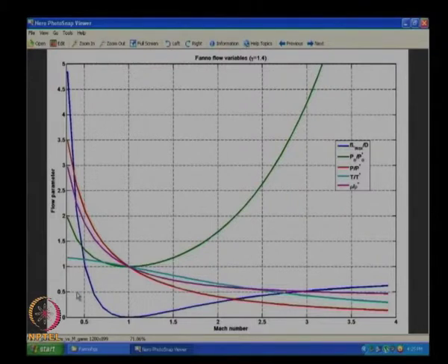That also says that if, let us say, the L max was 1 meter from here, this is arbitrary units, remember that. I am not giving correct units because f and D values are not given yet. So if we say it's 1 meter, by the time I go from here to here, let us say this is 0.65 Mach number, it would have crossed half a meter. It is changing Mach number very slowly while traveling long distances for the subsonic case. And especially at very low Mach numbers, it is changing Mach number extremely slowly while it is traveling long distances.